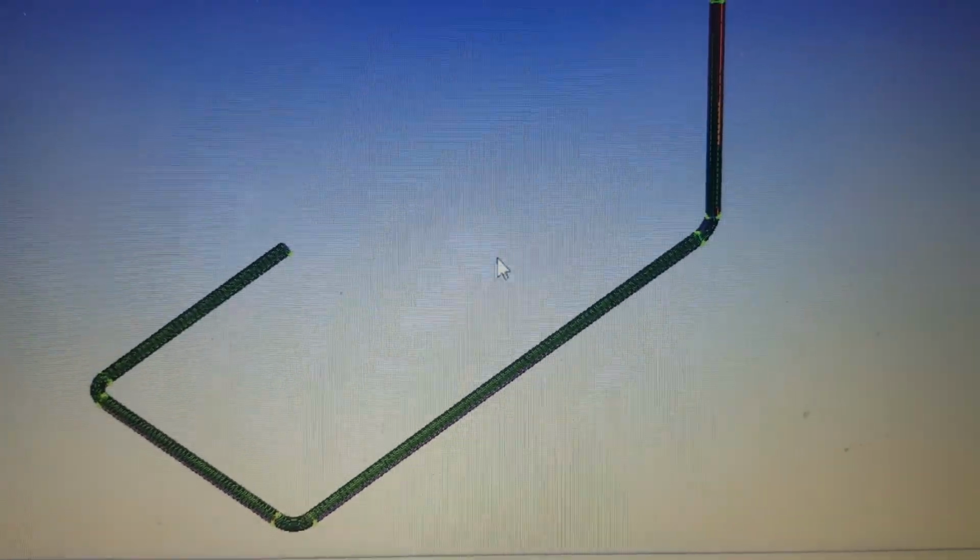Here you can see the coarse mesh of the bench model, which consists of 180,000 nodes. The refined version contains over 400,000 nodes. Once this step was completed, the mesh files were read into a case file for running the simulation in ANSYS Fluent.